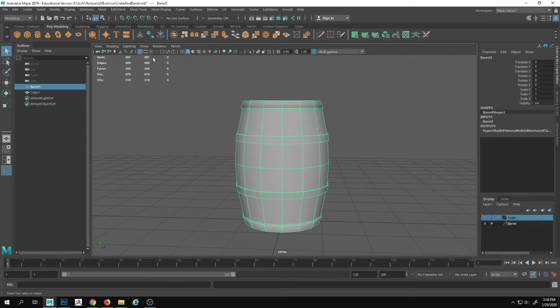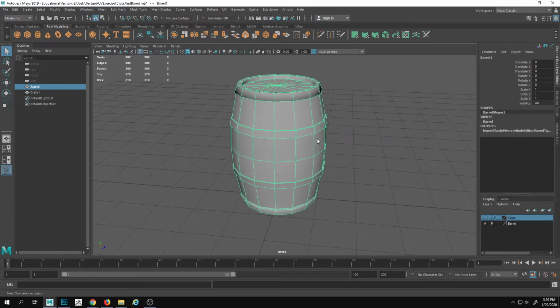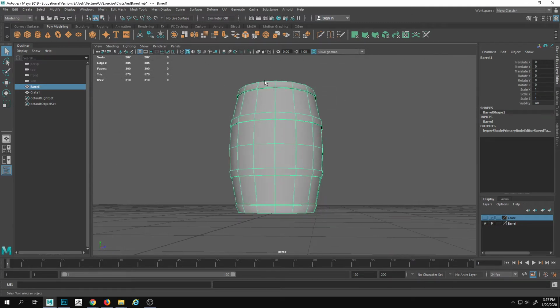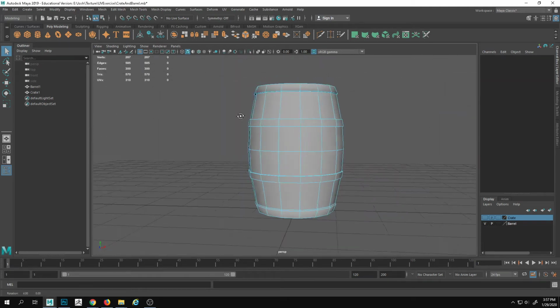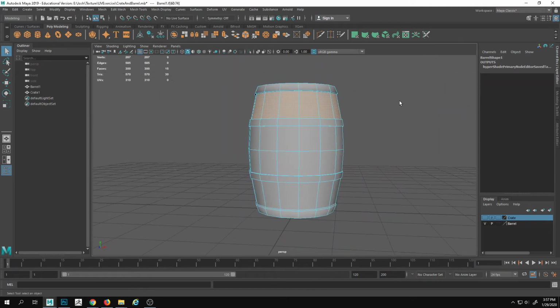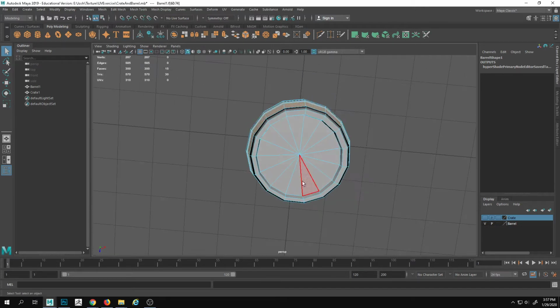Right now, I don't have a budget for this, but I'm trying to make it easy for a UV unwrap, and so I shouldn't have this thing be like 5,000 triangles. That's just a lot. So this is actually 570. That's helpful because I can find out how many polygons go around this ring by just selecting across here. I know that's 15 faces or 30 triangles, because faces are usually quads and triangles divide that by 2. So that's a lot.